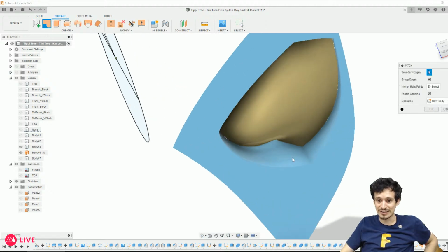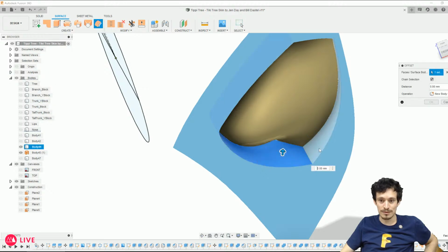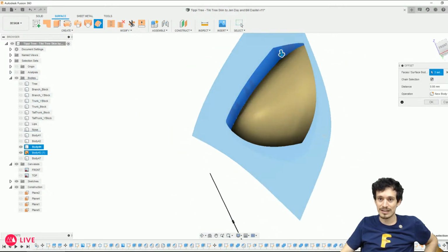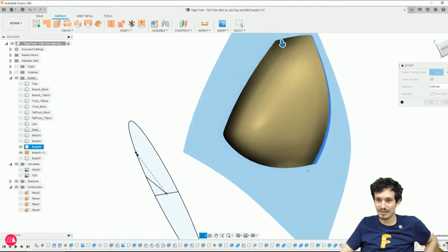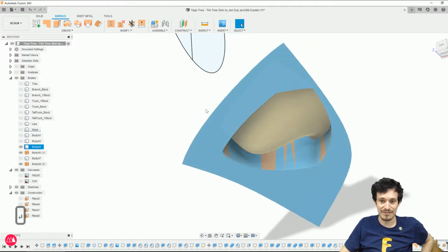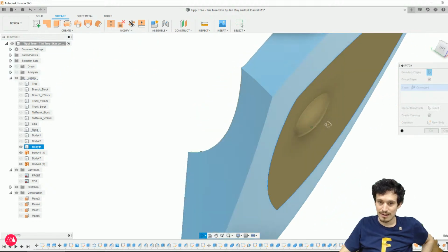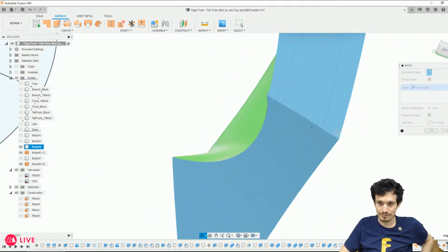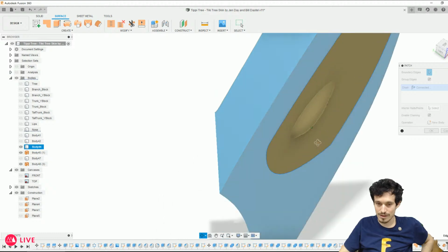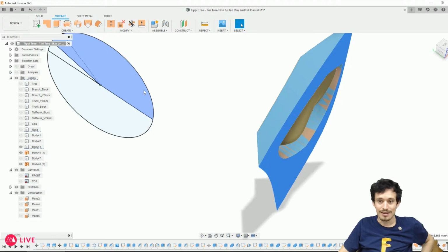So we have one surface. Now I'm going to go ahead and copy all of these other surfaces using the offset tool. 1, 2, 3. That's all of it. A 0 millimeter offset. So it's literally just duplicating that. And now I can do one more patch right here on the back. Boom. Uh-oh. That's not good. That means I have to, okay.